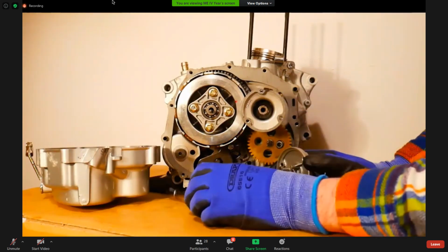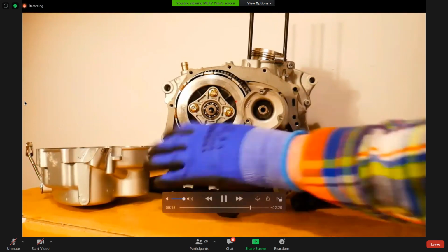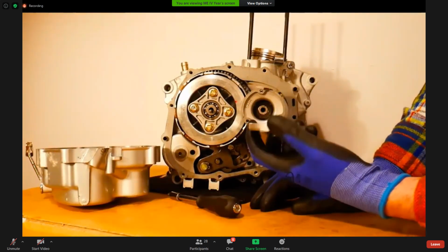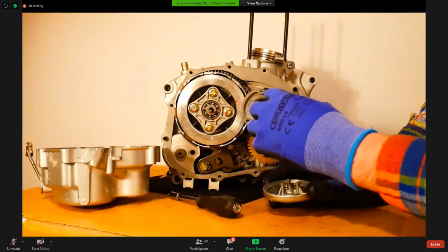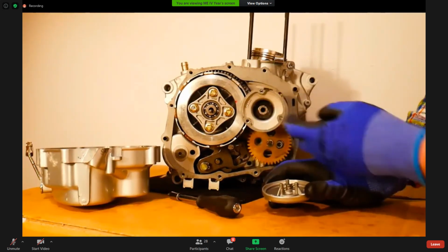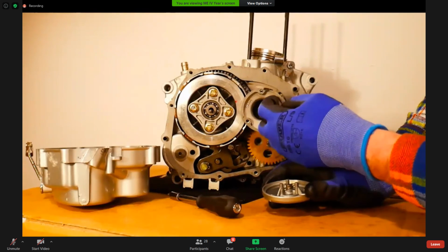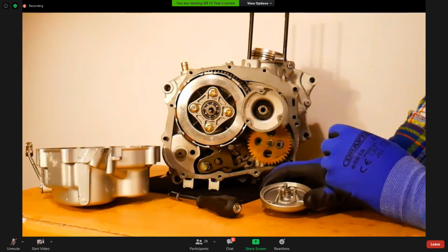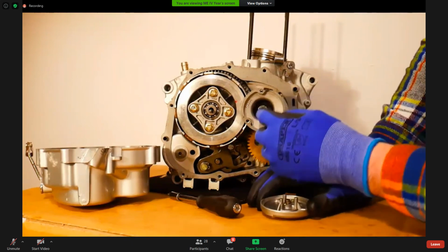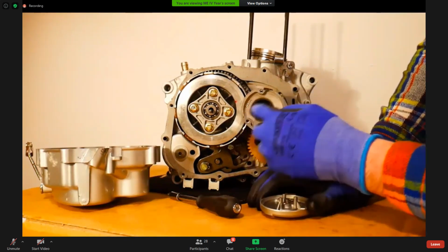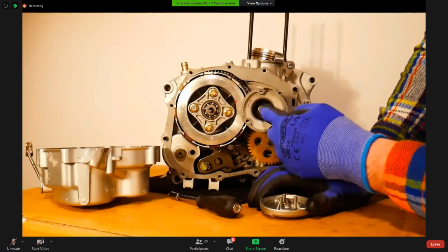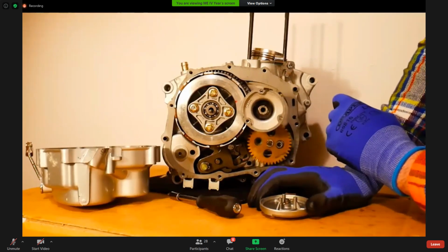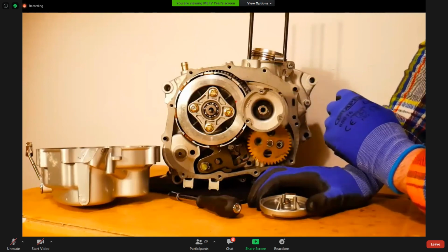And you will have to periodically remove the clutch cover. You will have to periodically remove this little cover from the centrifugal oil filter, and you will have to scrape out the dirt. So you'll see a little buildup of gunge around the edge. Okay. And then the clean oil continues on its journey into the crankshaft here. And then we have clean oil feeding into the engine.